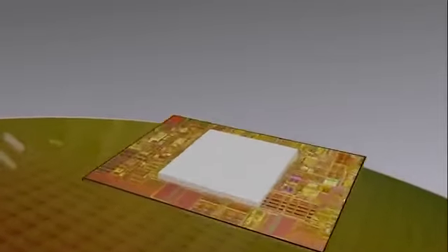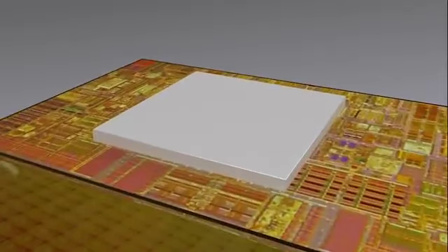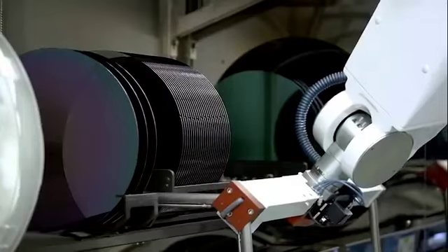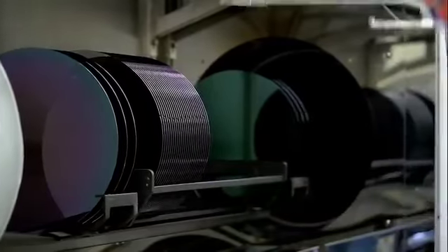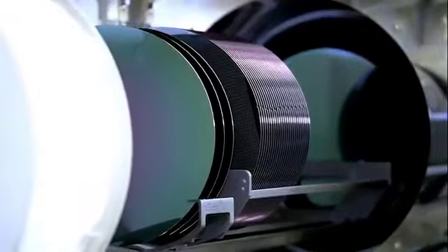Chips are built on a base wafer cut from a silicon boule. Depending on their size, several dozen or several thousand chips can be fabricated on one wafer. First of all, the surface of the wafer is oxidized in a high-temperature furnace operating at approximately 1000 degrees Celsius to create a non-conductive layer.